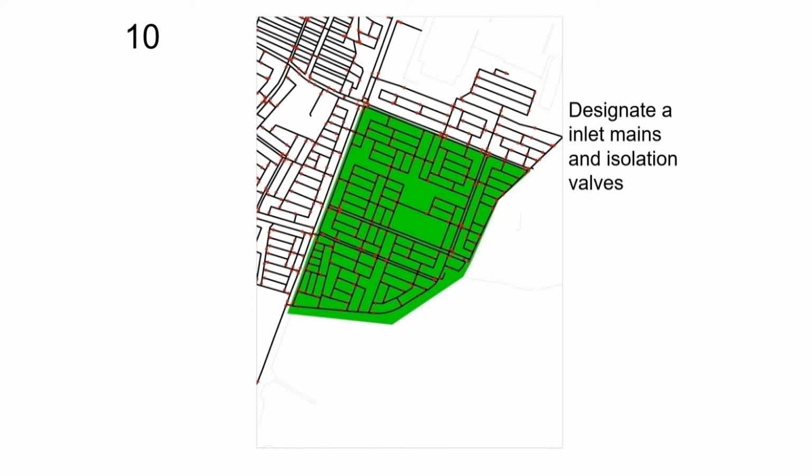The distribution pipe with 250 mm in diameter, the largest diameter in the area, was selected. It is located where you see a red arrow in the diagram. With both the network plan and on-site survey, we then assessed whether some existing valves can be closed to serve as isolation valves. We confirmed that establishing a block was possible by closing 9 valves.